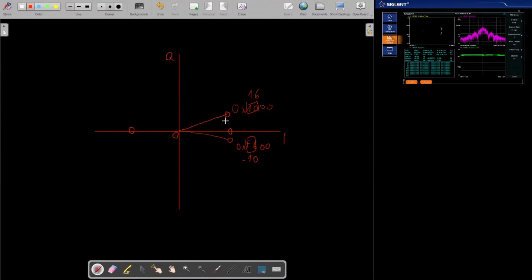And that causes the DC component to leak. Because if we take a look at this pair of points, we can see that the average is somewhere here. I'm not sure if I can use the word barycenter, but if those were masses, that would be the center of gravity. So that's the middle point between this point and this point of the constellation. So in our case, it's not 0, but we need it to be 0 to get rid of the DC component.